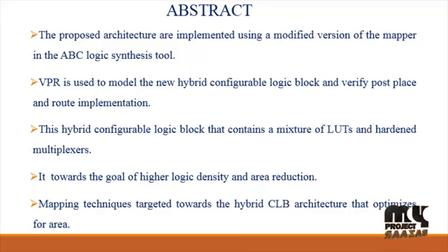This area could be large as it includes not just the logic function but the expensive programmable routing required to connect it. This potential waste motivates us to look for other ways to make use of these structures. Two factors affect this: one, the decoding logic may share the same select signal, and two, digital designs contain decoded multiplexers. The first factor, reducing decoding logic, is due to multiplexing buses.